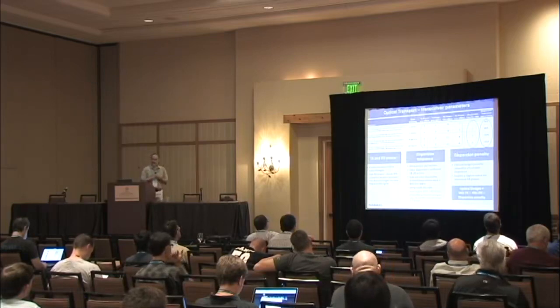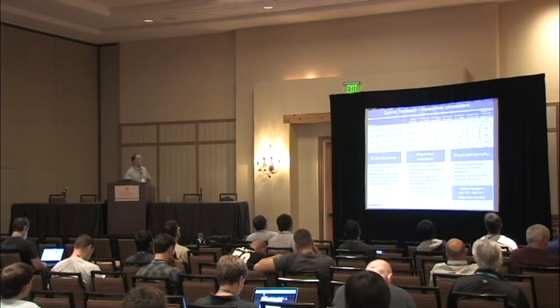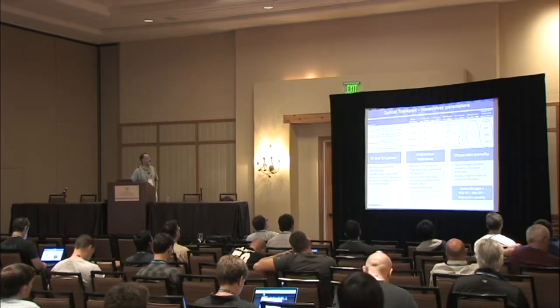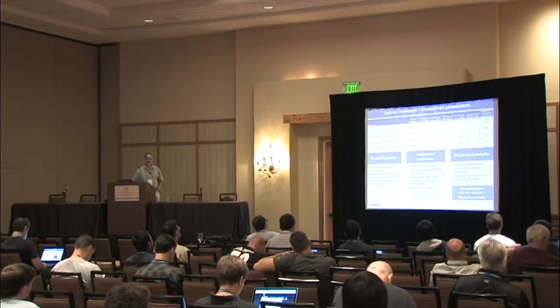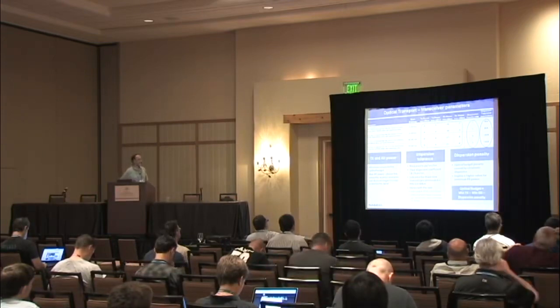Let's look at the transceiver parameters that are the basis for our optical budget. Transmit and receive power. Here in blue, I show the 40 kilometer and the 80 kilometer, both 50 and 100 gigahertz. Look at the transmit and receive power, the one in blue. You see that the starting point, the transmit power, is very similar for both of them, for the 40 and 80 kilometer. The main difference is in the minimum receive power. One is minus 16, the other one is minus 23. So that's the difference in reach, or capacity to reach.